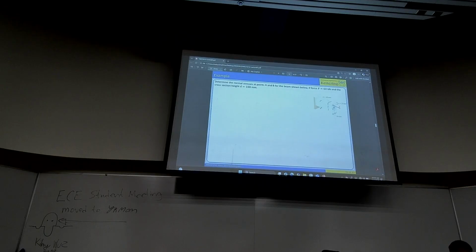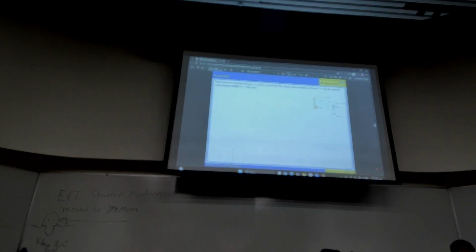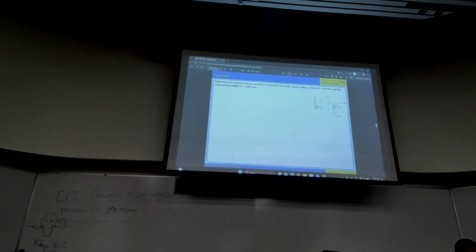When there is non-symmetry, that happens. So all those cases, this problem applies. So really the same thing, only dimensions, cross-section, shape changes. So the force is deployed at point D with some offset from C. Dimensions are given, and the goal is to solve for stresses at different points, A and B. Why A and B? Because these are the extreme points.